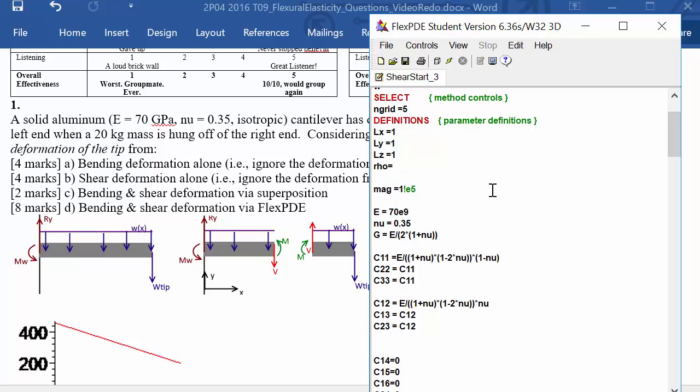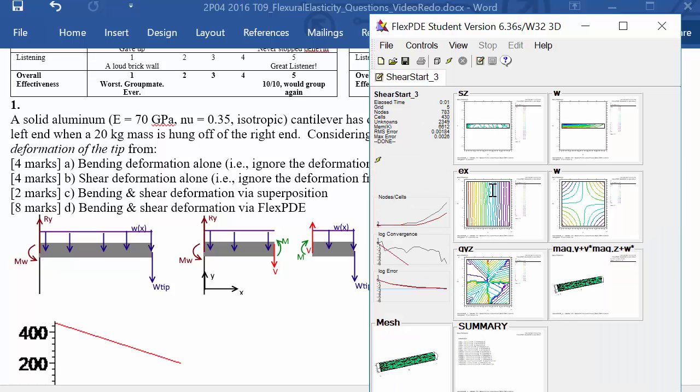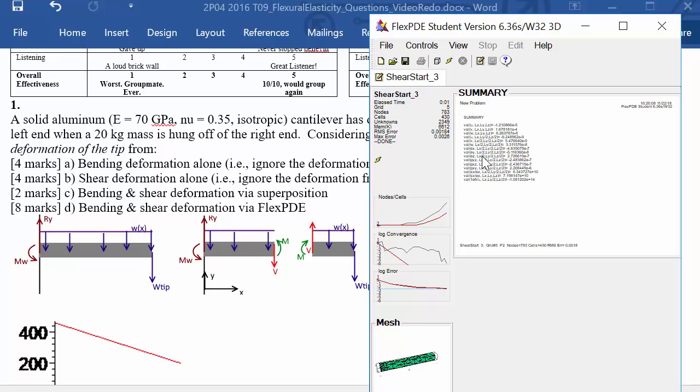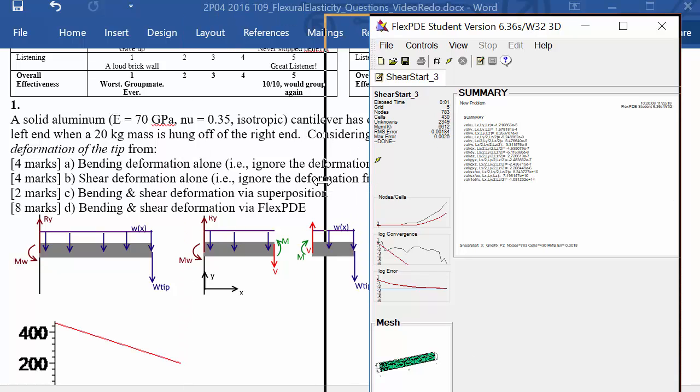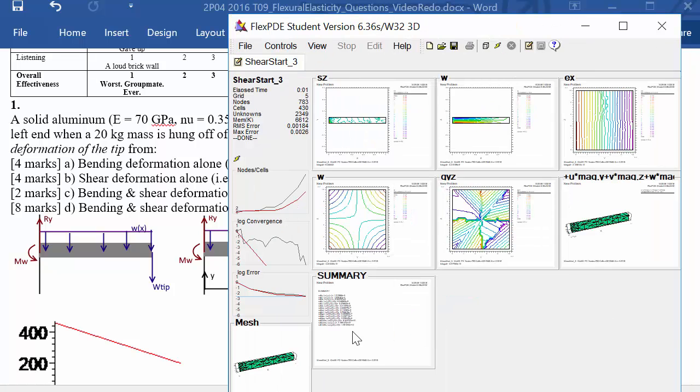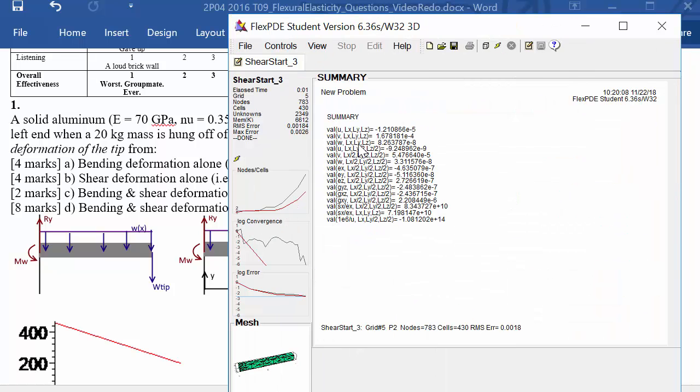Rho is equal to 2700, and we got to put in our dimensions, 0.1, 0.1, and let's see what we get. Okay, lots of funky pictures here. Magnification, we can't see anything. There's too many things in the summary table for it to report it accurately. Too many plots here. But what we were looking for is what the value of y displacement is, and we have 168 E minus 4.